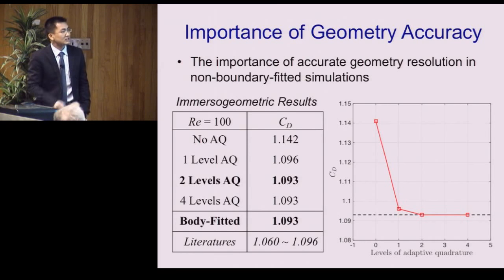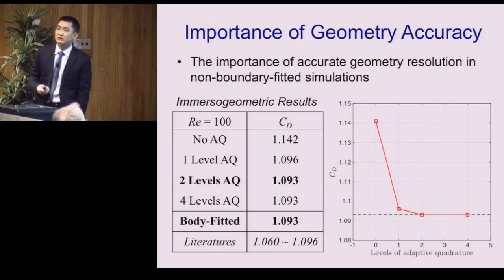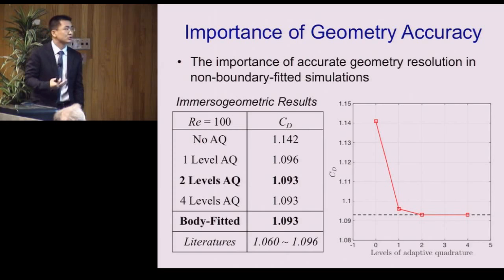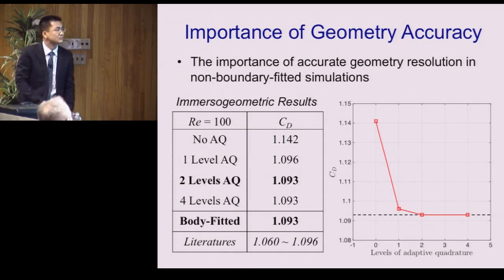And this greatly tells us that, well, geometry is not something we talk about every day. It's also something linked back to the idea of isogeometric analysis. We want to start to respect geometry in our analysis framework. When we start to respect that, you can see you remove the geometry error and you are able to converge to the boundary fitted solution in a better sense.